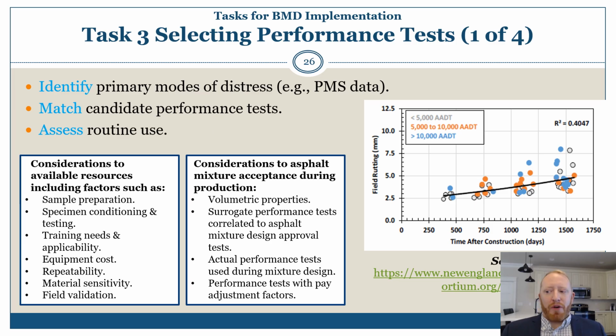Considerations to asphalt mixture acceptance during production, okay? There are many different ways to do that. All right, so that does come into when thinking about the test, because there are many ways to think about how you might bring BMD into acceptance. Maybe you do this test, or maybe it's different than the one you do at mix design. That's kind of a surrogate approach that's correlated to maybe a more complicated test at mix design, but then there's a more rapid one that you do in production. So thinking about that is important.